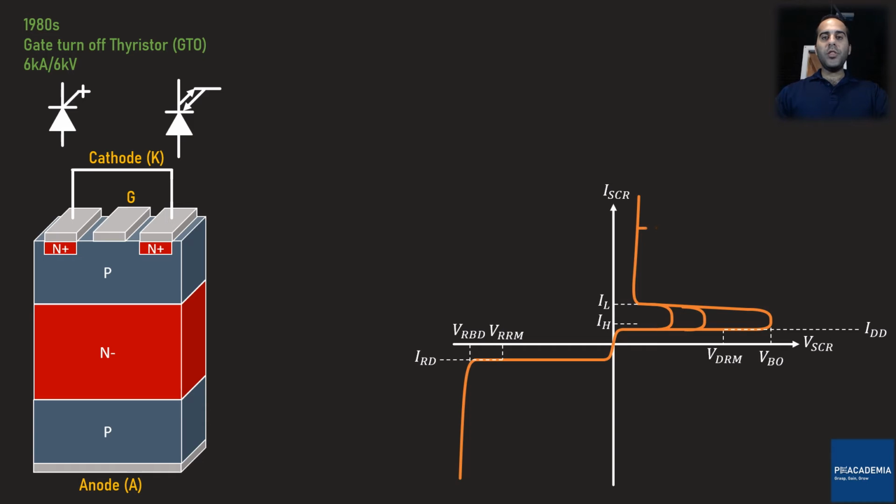First, the voltage over the GTO increases, but the forward current remains almost intact. This is because of the recombination time of the accumulated charge carriers in the top P semiconductor. What happens next is that the current drops and finally gets smaller than the holding current. This turns off the GTO.